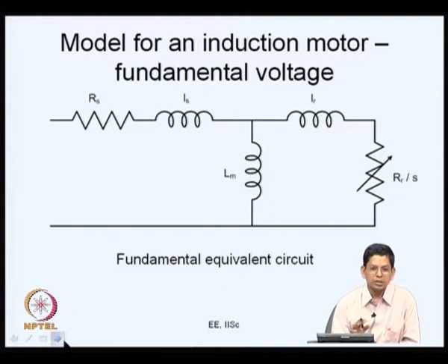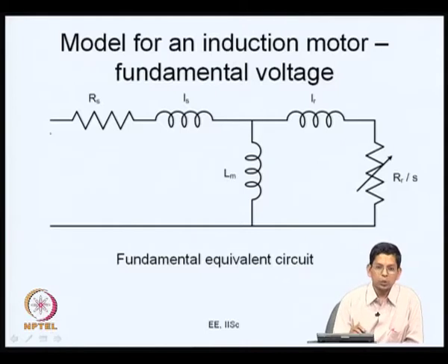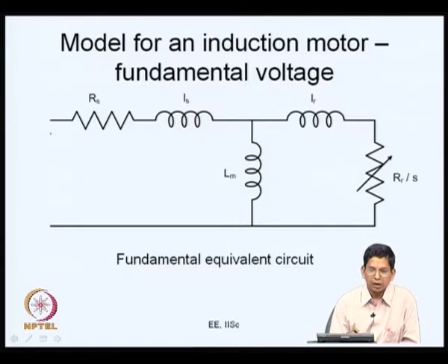Now, this is all a kind of review of Fourier series, so that we can use Fourier series effectively to calculate the fundamental voltages and harmonic voltages of several different PWM waveforms. The next issue is, when harmonic voltages are there, what are their effects? What gets applied to an induction motor fed from a voltage source inverter is not only the sinusoidal fundamental component; harmonics also get fed there.